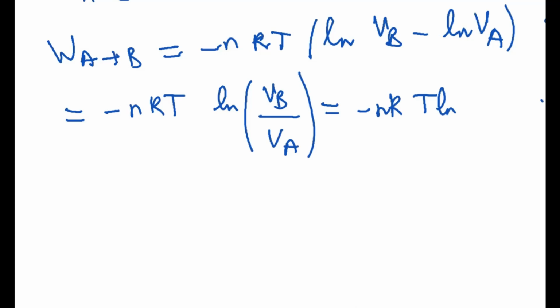So my advice is to make notes in the beginning about what you know from the wording and what you can guess easily from the wording, mostly using the perfect gas law, and if it's adiabatic, PV^gamma equals constant. But for now, we just need to replace VB by V1, that's it. So let's do it. So it's going to be V1 over V2.